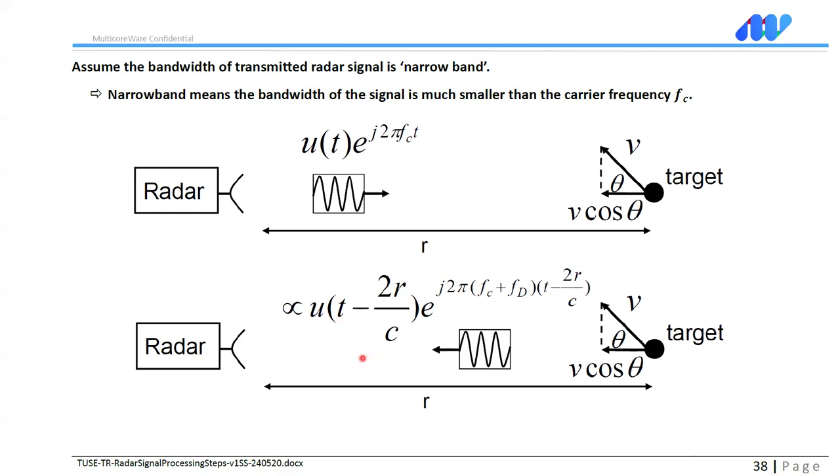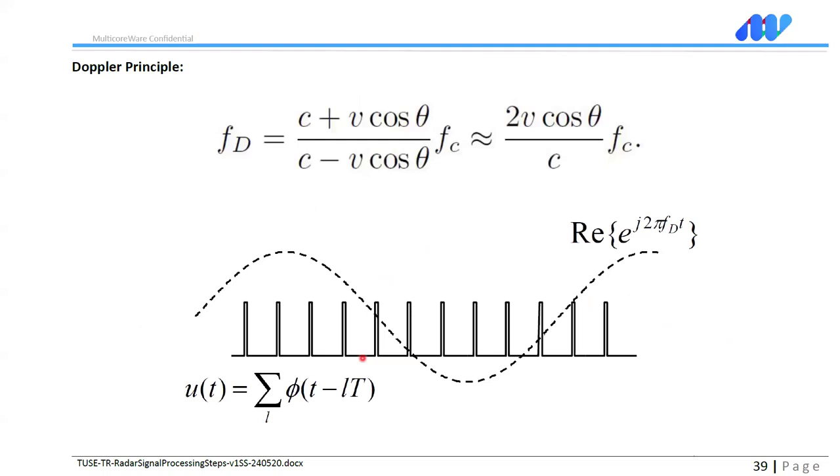And this variation is slow. You cannot see it within the pulse. You hit it, velocity is almost the same. So you need to kind of go through the slow time. You take sample, sample, sample, sample, and each one of them is one axis, and you put this second set of vectors on the side, third, fourth, and you create a whole matrix. And this matrix becomes two-dimensional. One axis is slow time, the other axis is fast time.